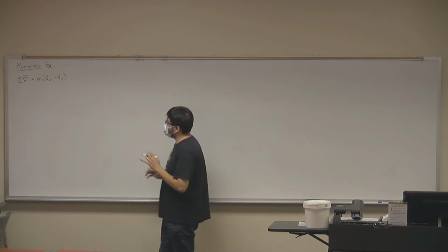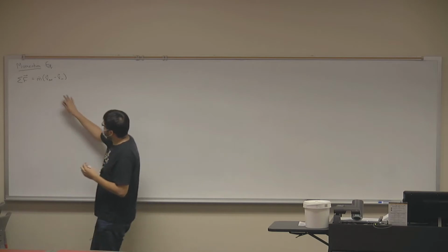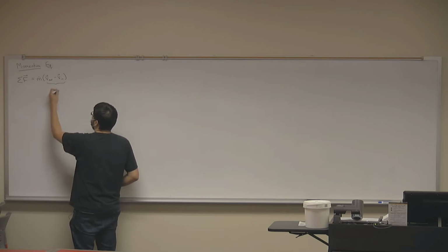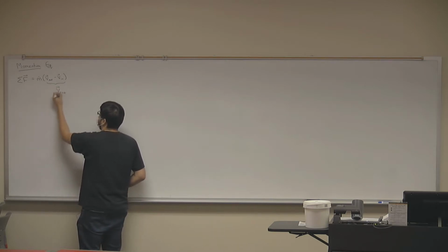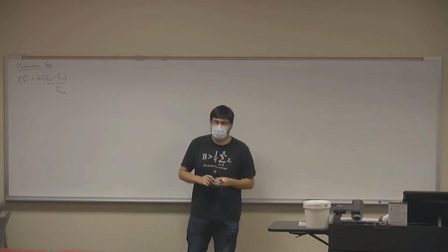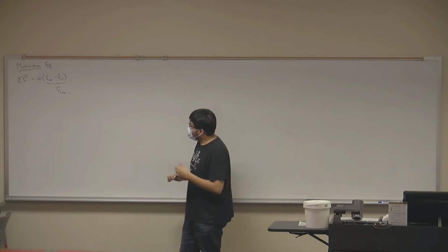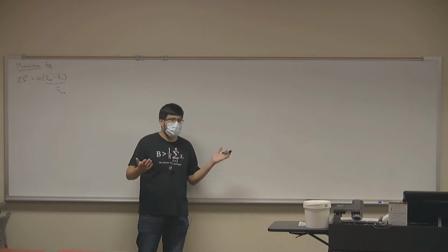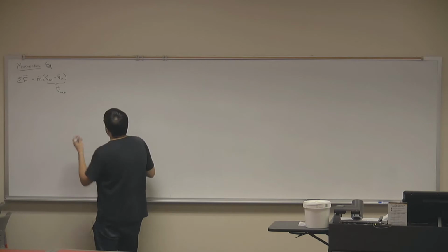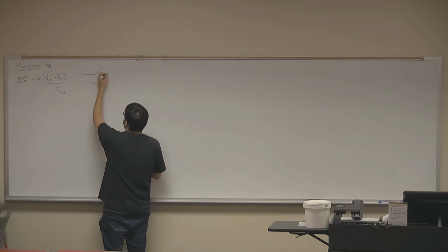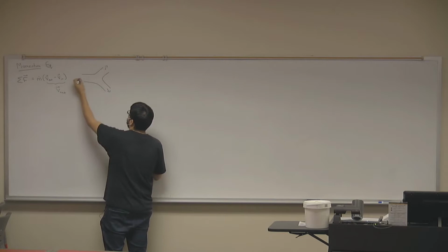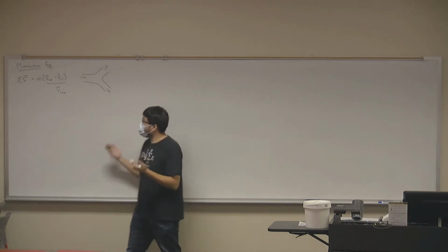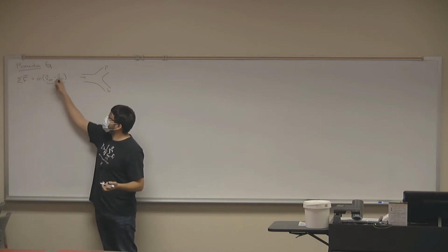The reason I want to point this out is because this V out minus V in is essentially equal to the net flux of velocity, which was our intensive property, through the control volume. We call it V out and V in because some of it has to come in, some of it has to go out, right? However, you may have situations where you have two outlets and one inlet, or vice versa. You can have situations where you have two inlets and one outlet. When that happens, remember, you'll have multiple V out or V in terms.